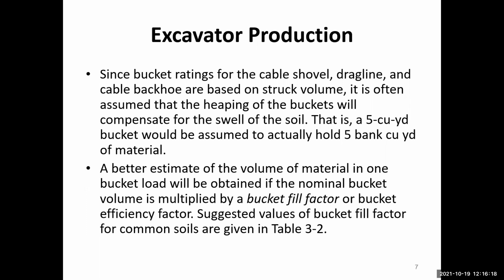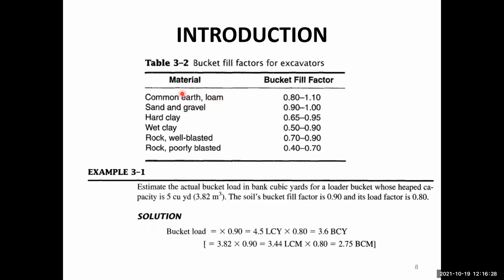This is the table for the bucket fill factor. The bucket fill factor depends on the type of the material. So for example, if it is common earth or loam, the bucket fill factor can be taken between 0.8 to 1.1.